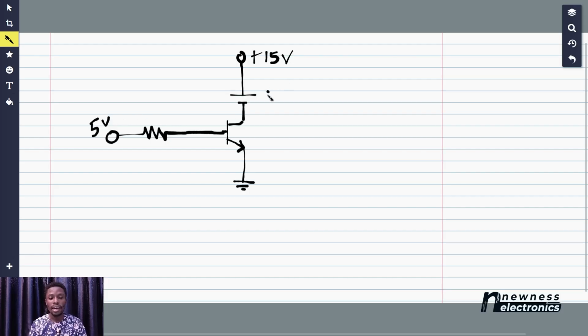Now, this battery is rated... we are creating an assumption now. Let's assume that the battery you want to charge is rated 10 amp hour. If you are close to batteries, you will see that they write their ratings there. A 10 amp hour battery, and you want to charge it faster, maybe with 3 ampere. You need 3 ampere of current flowing through it, so that in under 3 hours it should be completely charged, right?